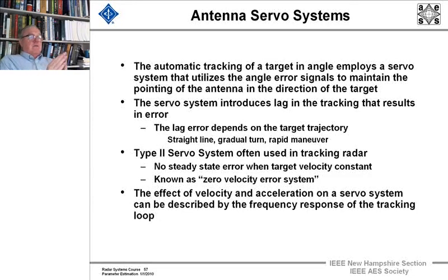And the lag error depends on the target trajectory. The lag error will settle down to little or nothing if the target is on a straight line. But if it's taking a gradual turn or making rapid maneuvers, there can be a significant lag error. And we'll see later on where trackers will veer off before they get back on.